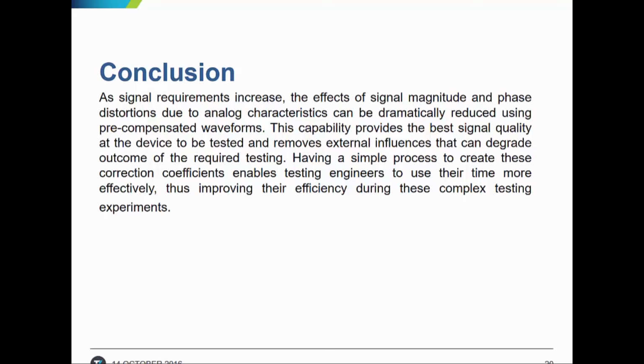So the conclusion here is that in order to create signals to test your devices under test correctly, in many cases it requires that you de-embed some of the losses associated with the actual generation equipment and also the cables and connectors and devices that are associated with the network through which the signal will pass. So this is a very effective tool that we provide in order to give you a simple way of doing these compensations without having to write MATLAB code on your own to do this. It's very important to be able to have this capability, and we've tried to provide the easiest method in order to give you this capability.